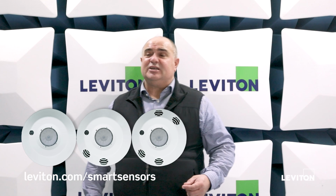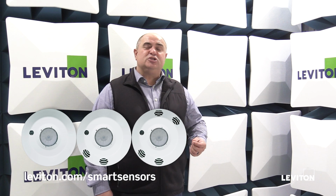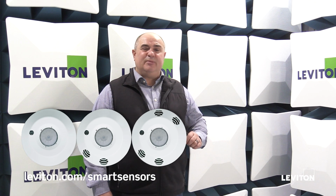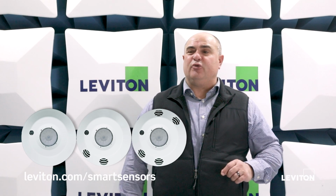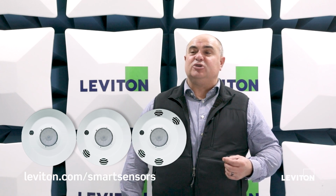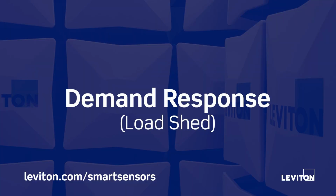In the ceiling mounted sensor, we did include the ambient hold off technology that we have found very useful in Wallbox applications. But again, that is not the ability to dim the fixture. So the hold off does not meet the energy code requirements for true daylight harvesting. But in both of these technologies, we wanted to make sure that we were able to do the plug load control or receptacle control. In addition to that, the term demand response.